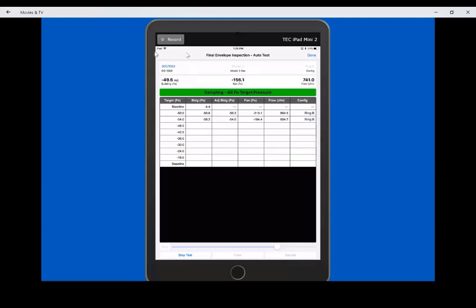So you can see it's sampling the data for 48 now. The CFM50 is showing over here, and the fan pressure. We usually don't think about the pressure at the flow sensor of the fan, but that's being displayed here. That's being converted to flow based on the device we're using, the duct blaster, and the ring configuration that we have.